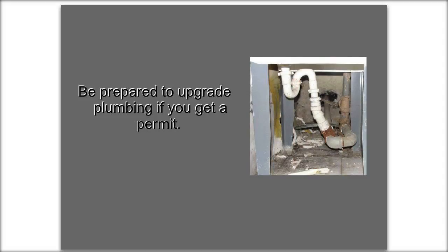Lots of homes are. And so if you have an inspector coming to look at your graywater system and you're going to be altering your plumbing, you're going to be tapping in to put in your diverter valve, most likely they're going to want you to upgrade the rest of your plumbing to meet the current standards. They're not going to make you replumb your entire house, but anywhere you touch, usually up to the main sewer line, that's usually where they're going to ask you to fix it.